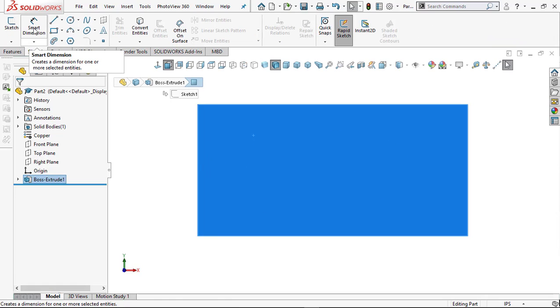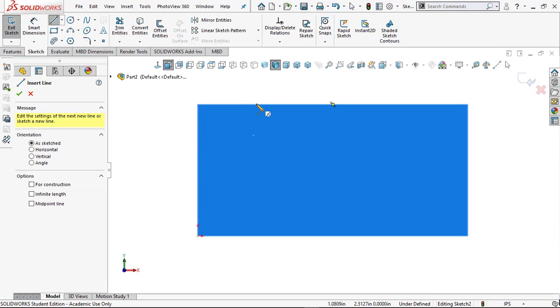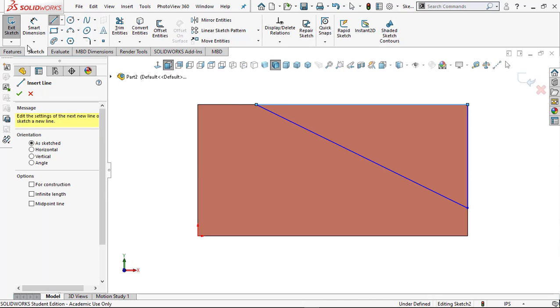Now I'll come back over here to sketch. I'll create a new sketch. I'm just going to click up here on this edge. Click right there, and it brings up these cool drafting triads and tools here. And I'll click on this edge here, and I'll snap to that corner, move here and close off that sketch. That looks pretty cool.